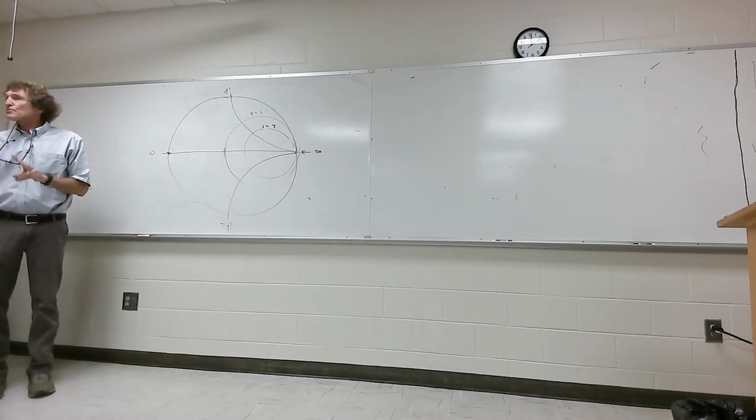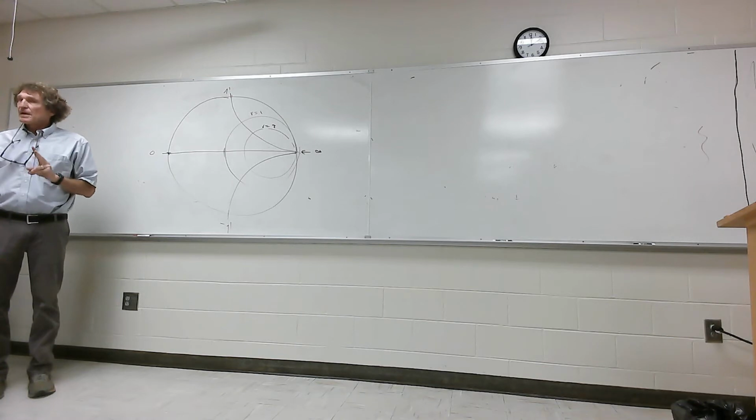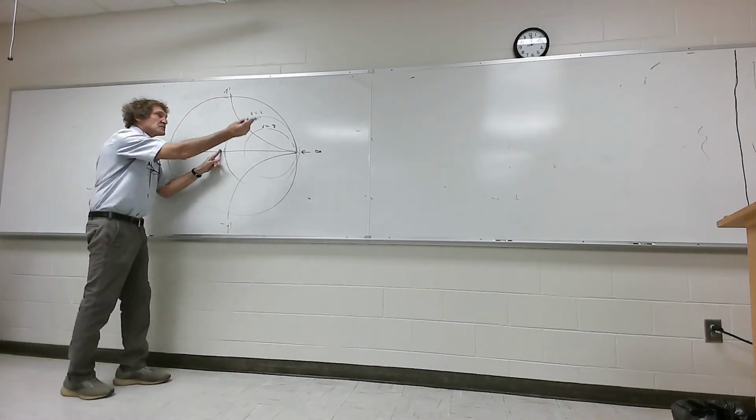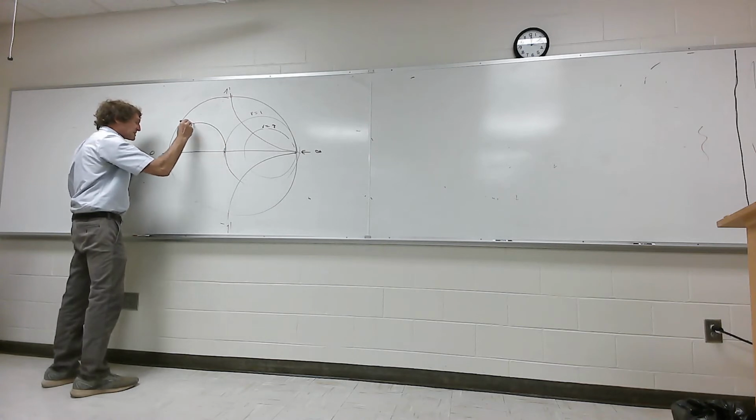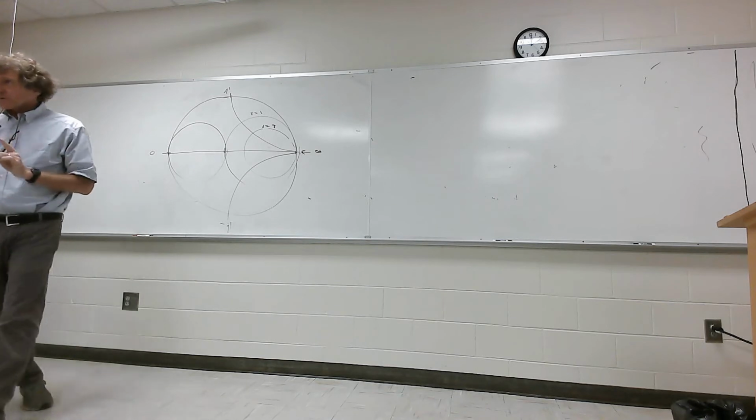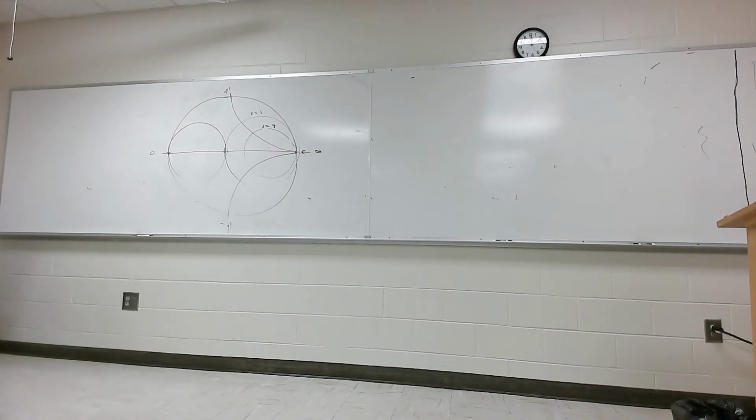Here's the difference. A rotated Smith chart, please hear me, simply takes this R equals 1 circle and it pivots it and rotates it right here. So you get the same exact circle, but this is called the rotated 1 circle. And you're going to see why it's important. Y'all follow? That doesn't appear on a normal Smith chart.